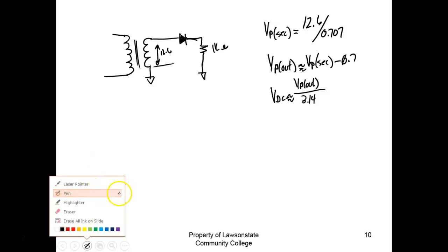varies at a precise rate. So I know that RMS is actually calculated by taking an infinite number of instantaneous voltages around the sine wave, right? Square them, so that way your negatives become positive. Take the average, and then take the square root of your answer. If it's a sine wave, that always comes up to be the sine of 45 degrees, which is 0.707.